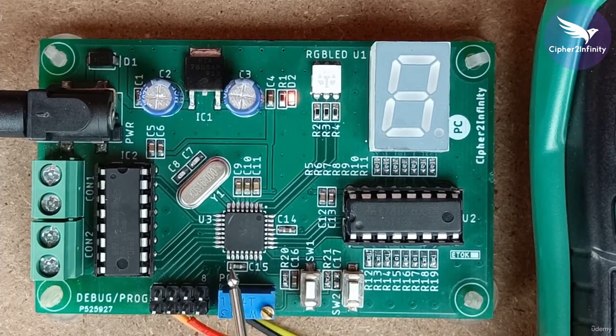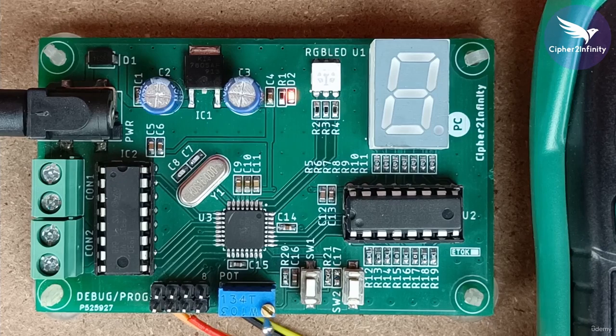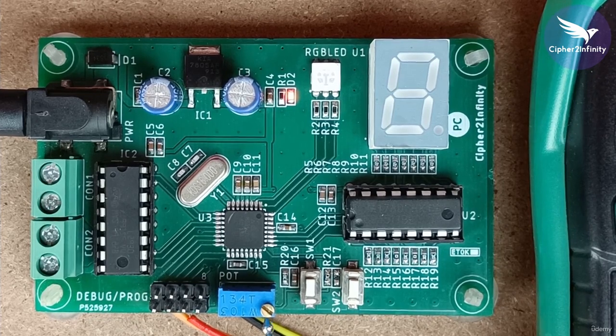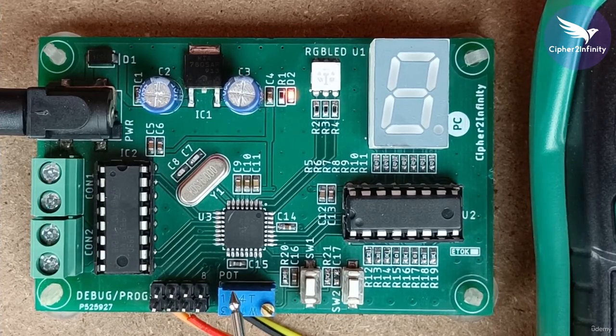Okay, so that's how you have to do the testing and troubleshooting. You just have to check the voltage on the center point, check whether the preset is properly soldered or not, and check whether the plus 5 volt or the supply voltage is available on the first terminal of this preset with respect to the third pin of this preset. So that's how you do the testing and troubleshooting in case of the preset section.